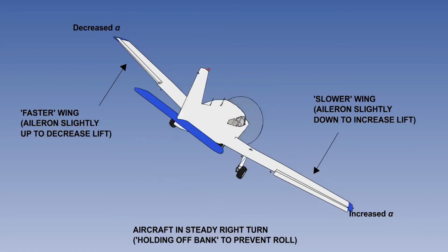In a descending turn, the power is likely to be at a low or idle setting. In the event of a stall, the pilot would need to counteract the forces arising around all three axes as the power is increased through most or all of its range during a stall recovery. As with any situation, it is important for the controls to be coordinated, and particularly so where the aircraft is at or close to the stall, to prevent an inadvertent spin.